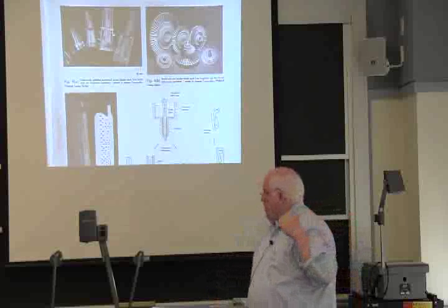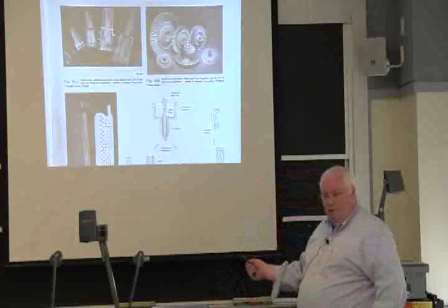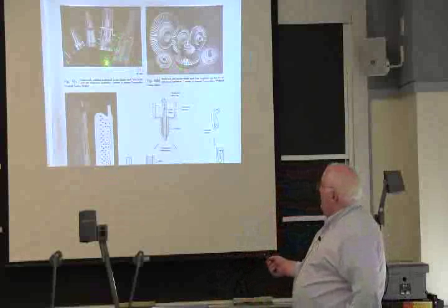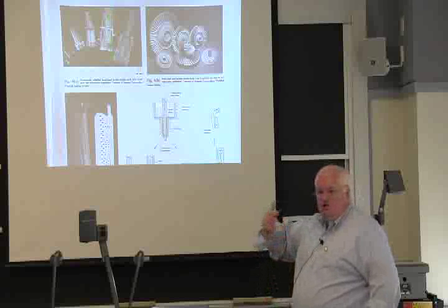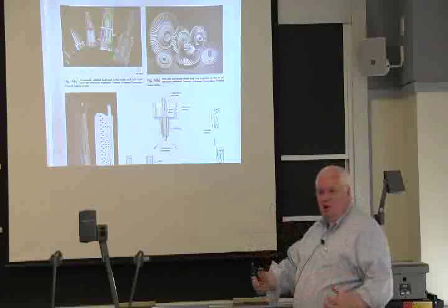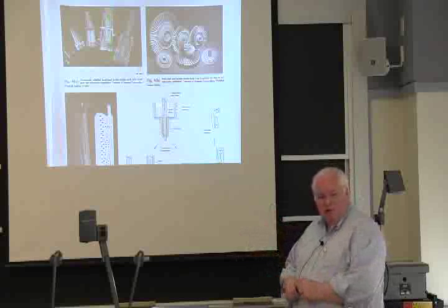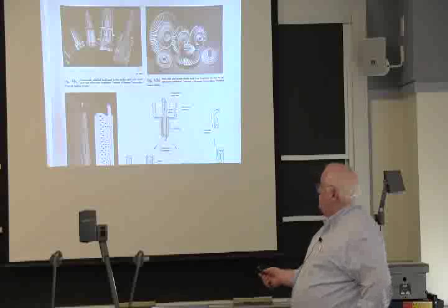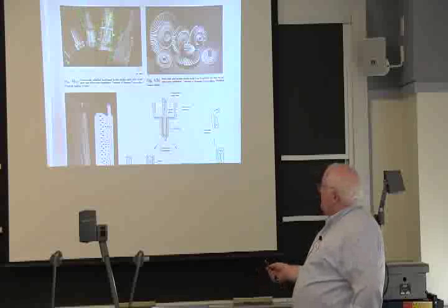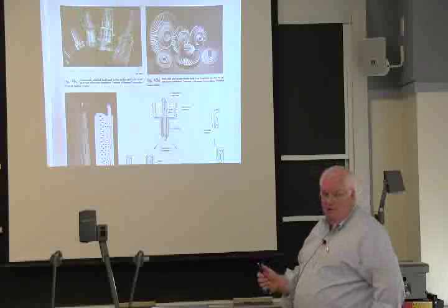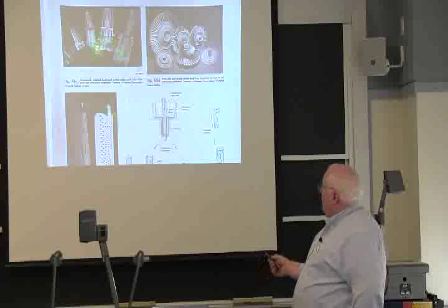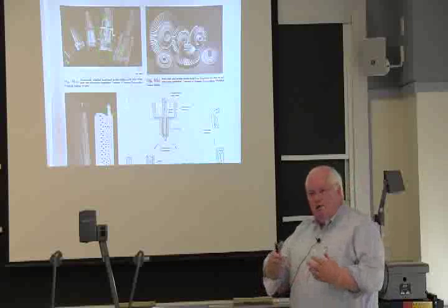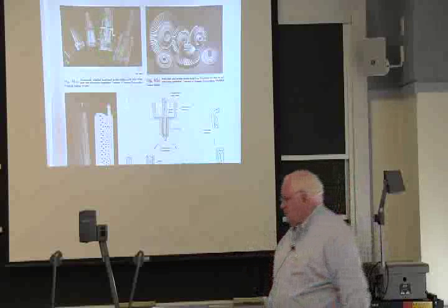If you go up here to General Electric Lynn, where they build these turbines for the military now, you'll see machine tools just taking solid chunks of steel and making compressor blades by machining them from solid bars of material. When you get to the hot section, you have to use nickel-based alloys. They don't machine so well. They're very difficult to machine. And so they actually cast them. In the 50s, they'd be equiaxed castings, lots of little crystals.